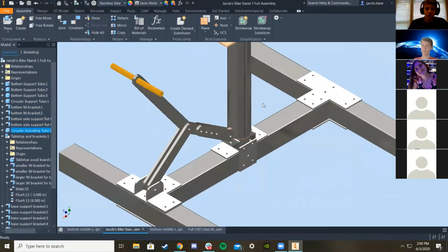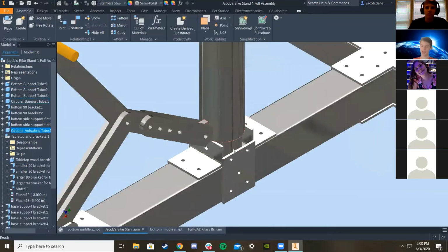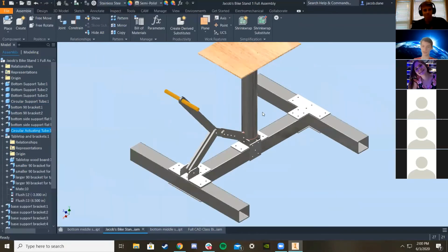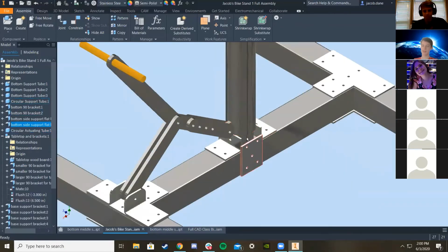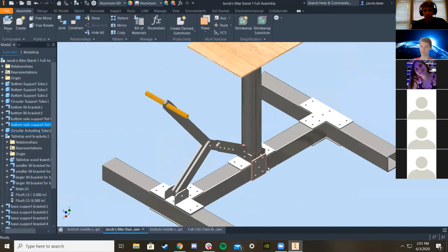And so what you have to be careful about is, in the video, as you saw, he had 2 tubes, and the outer diameter, okay, so I'm just gonna explain in terms real fast. For circles, there's an ID and an OD, or inner diameter and outer diameter. The inner diameter is just the diameter of the hole, and the outer diameter is the diameter of the actual edge of it. And so what he had is he made sure that the outer diameter of the smaller tube is opposed to the outer tube's inner diameter.